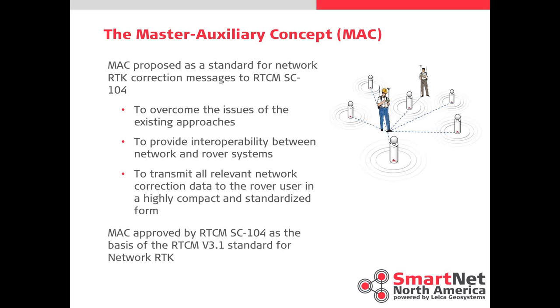So the concept that came out of this SC104 was the Master Auxiliary concept. The MAC was proposed as a standard for network RTK corrections. It was proposed to overcome the issues with the existing approaches, to provide interoperability between network and rover systems, and transmit all relevant network correction data to the rover user in a highly compact and standardized form. It has been ratified and accepted, and it is the industry standard for network RTK. That means everybody had to accept it. Leica, Trimble, Topcon, all the major players had to accept this to be the standard, and now it's incumbent on everybody to adopt that standard.